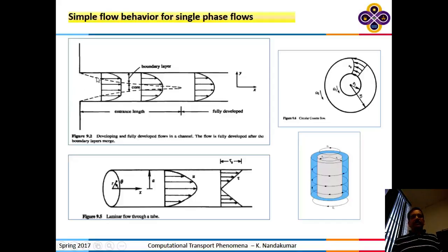Okay, but as it goes through that, you'll find that the fluid next to the pipe wall sticks to it, right? So there is a small curvature that develops in the velocity profile, and the flat part is still remaining there in the middle, and this is what is called a boundary layer. And as you go further down, the boundary layer essentially grows, as shown by the dotted line. And once you find that the boundary layer is fully grown, the velocity profile reaches your expected parabolic profile for which you can analytically solve. But in the region where it's called the entrance region, developing length, you cannot solve it analytically.